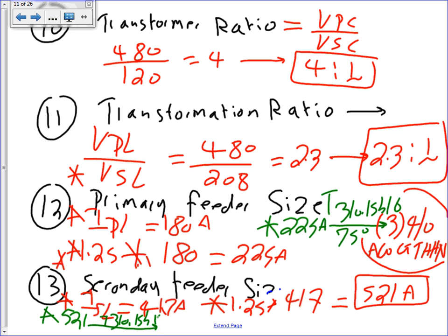310.15(B)(16). Can you read that even? And that will get you what size? How many conductors? I'm going to have a full neutral. I'm not going to rate the neutral for the time being. I don't want to go through the rating of the neutral. So how many conductors? I'm going to have 4 conductors. Are you paralleling? Okay. Let's just not parallel now.